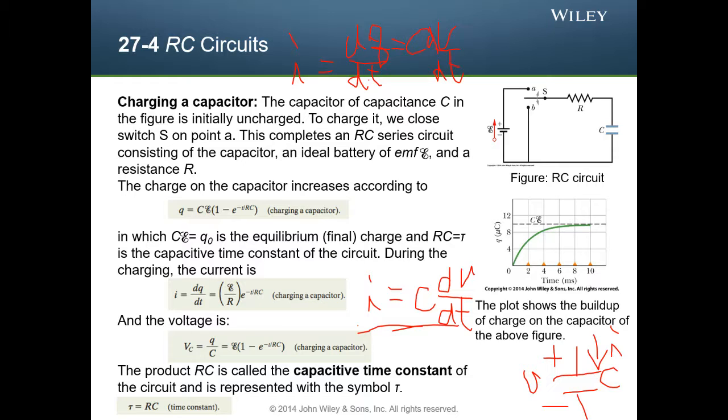So you take the inverse Laplace transform of this term, and you will have x(t) equals x(0) times exponential to minus 1 over RC t, something like this. This is the homogeneous solution. And of course, besides the homogeneous solution, you still have this term.